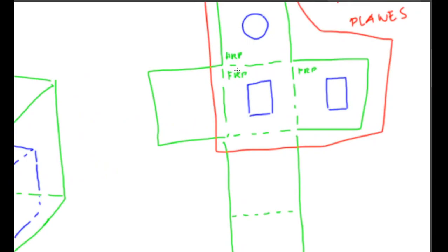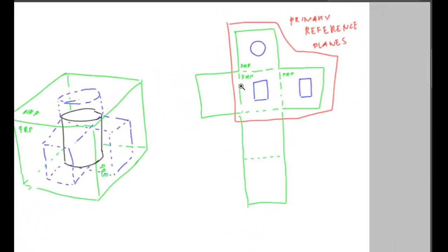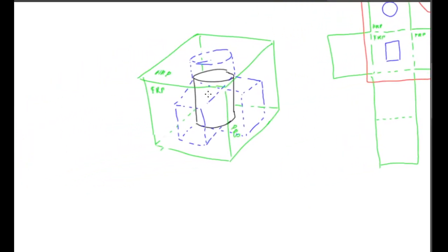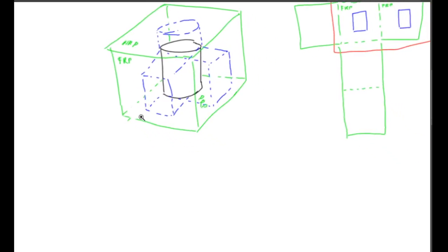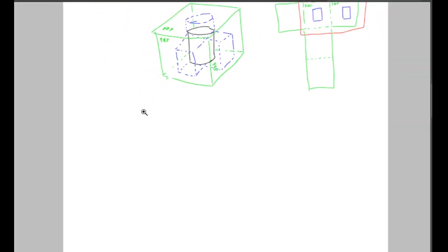Okay, the folding line here separates the two views, and it's more appropriate because this glass box here is infinitely expanding now. So it's sort of easier if we just draw the folding lines here. Okay, so if we try to draw that, we should get something like,